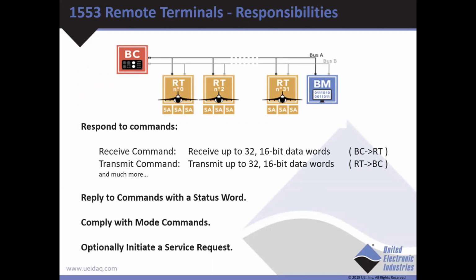The RT is responsible for handling commands. If it's a receive command, it needs to receive the data. If it's a transmit command, it needs to transmit its data, as well as other commands. It also needs to reply to commands with a status word so the bus controller knows whether there was an error. It also needs to comply with mode codes or mode commands, and the bus controller actually controls the RT itself with these commands. And then the remote terminal can optionally initiate a service request so the bus controller pays attention to it.